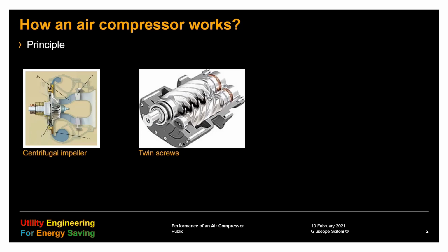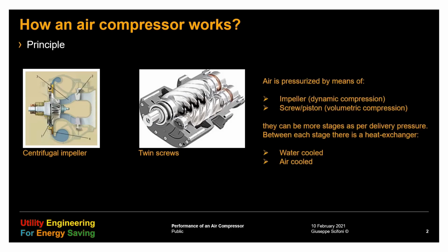Since the compression process is generating heat, the heat must be taken out with air or with water. The centrifugal machines are mostly water-cooled. On top, the screw compressors can be lubricated or not. The lubrication offers an advantage that we will see later on.